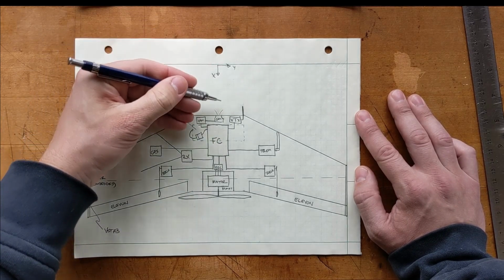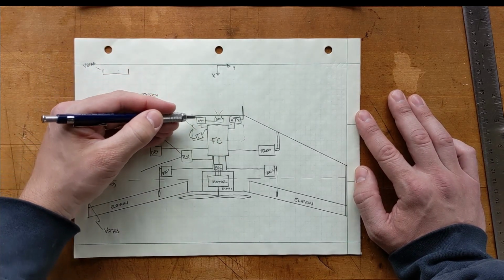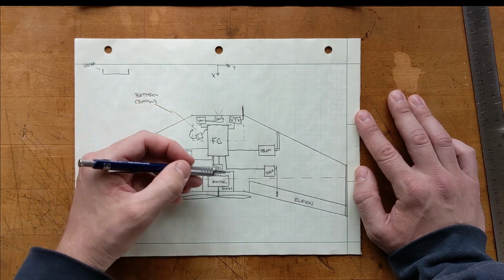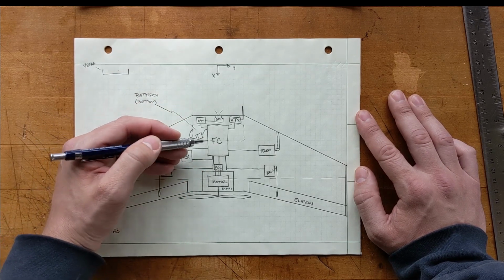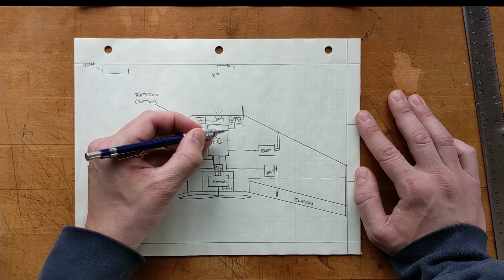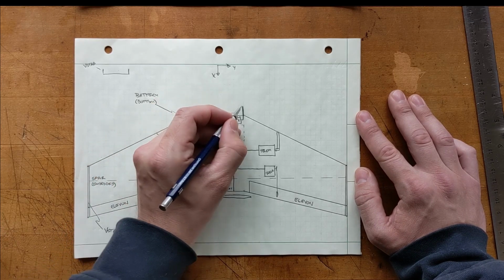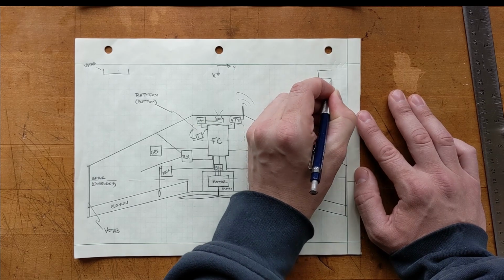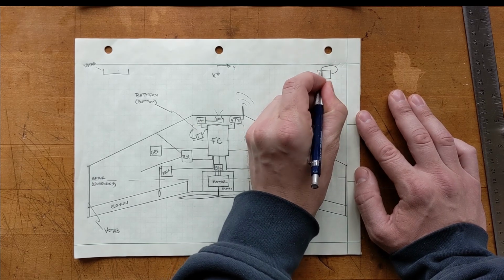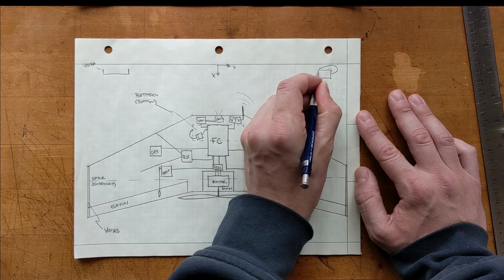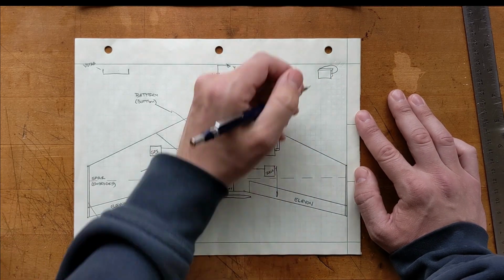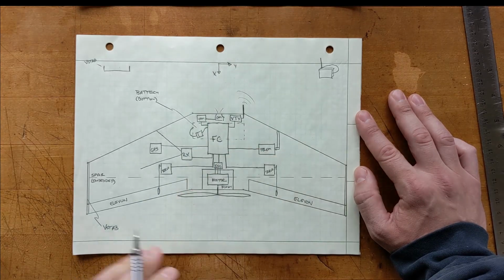So we'll have image coming into the camera, goes into the board where it can record it, sends it to the flight controller. Flight controller will overlay the on-screen display, send that signal out to the video transmitter, and that will send it to our goggles on the ground. Not bad, with its own little antenna.